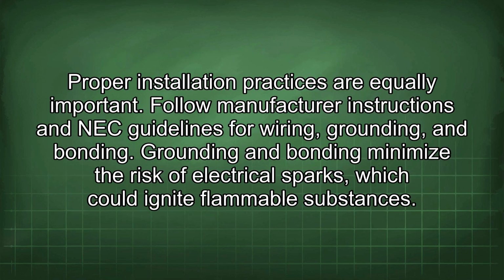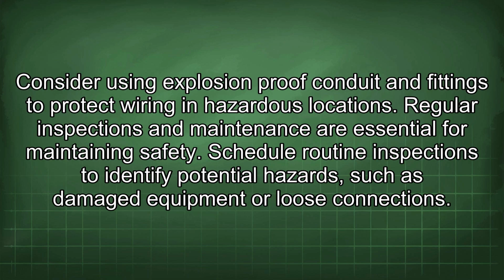Proper installation practices are equally important. Follow manufacturer instructions and NEC guidelines for wiring, grounding, and bonding. Grounding and bonding minimize the risk of electrical sparks, which could ignite flammable substances. Consider using explosion-proof conduits and fittings to protect wiring in hazardous locations.